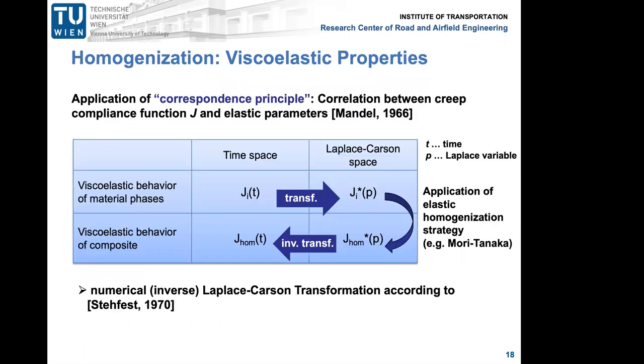And now, to provide a formally elastic and thus very convenient description of the viscoelastic problem, the time-dependent creep compliance, which is part of this power law model, is represented in the Laplace-Carson space.